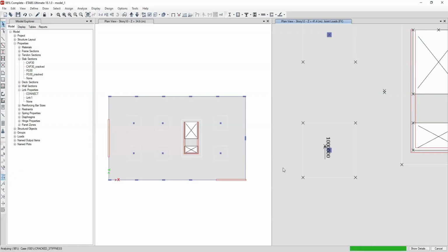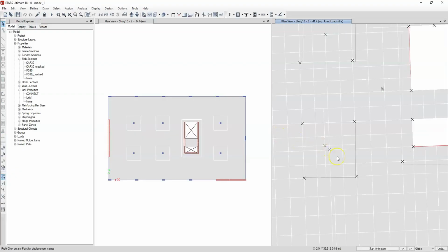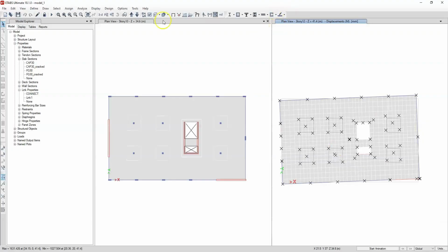On the other hand, this alteration is not dramatic because, for one, it is small, and additionally, we are also going to take into account the exact placement of the center of rigidity through an expression that we are going to apply. But it is normal that the center of rigidity will change its position because the stiffness of the elements is actually changing in height and the relative distribution is also distributed differently.